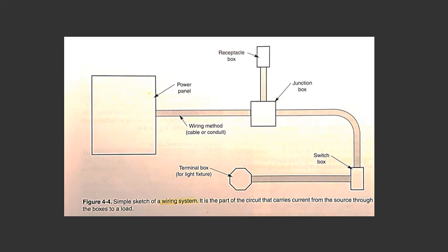Wiring systems. Conductors for carrying electricity are commonly called wiring. A wiring system includes the wire, its insulating cover, a protective cover, and connectors that fasten it to an electrical box. See Figure 4-4. In some systems, the protective covering and the wire are purchased separately, and the electrician assembles them on the job. In other cases, the protective covering is insulated during manufacture.